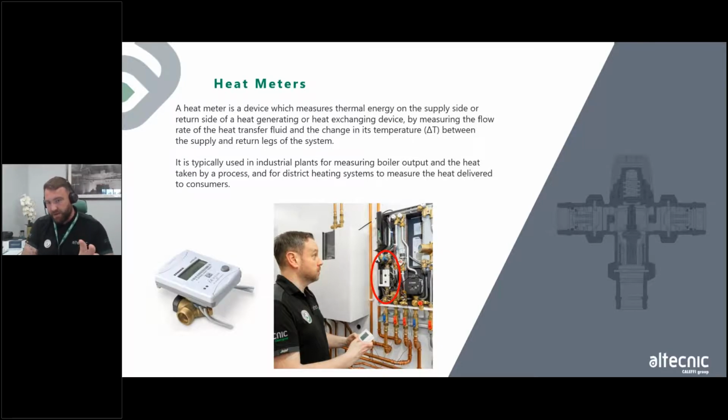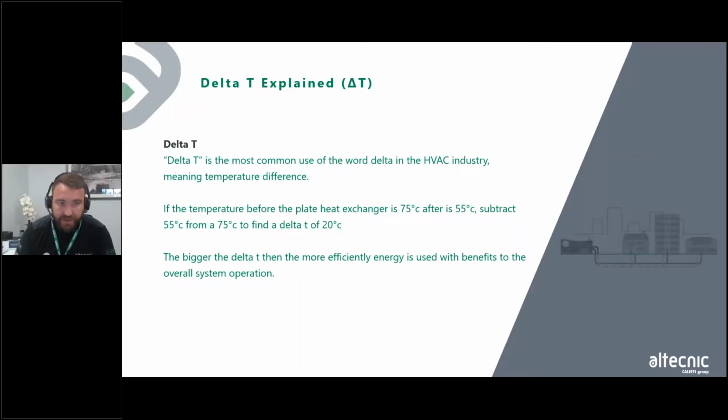And the heat meter will allow billing companies to take those readings and bill each individual apartment for the energy that they are using from that district heating centre. They're generally supplied on the return leg of the HIU. So once the hot water has gone through the HIU, we then start to record it, so we can make sure everyone's getting billed correctly.